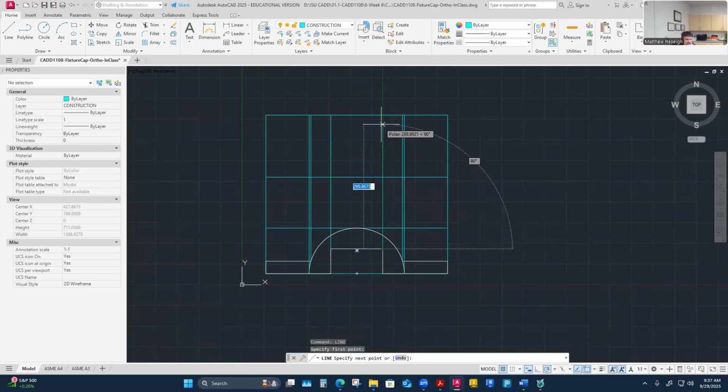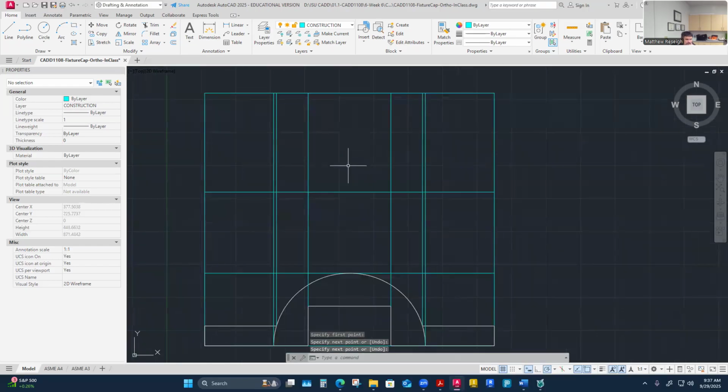And where it is symmetrical from front to back, I feel like I could draw in half of that shape. Maybe that's not any easier than just drawing it. I think I may draw half of it over here and mirror it across, rather than draw half of the front and mirror it to the back. I just feel like for me, it makes more sense, but you could do it either way. I'm just going to draw the circle and trim it with the little circle, probably half here to that hole and then mirror that. Probably not with the hole, but I'm going to mirror over and then add the hole in the center later.